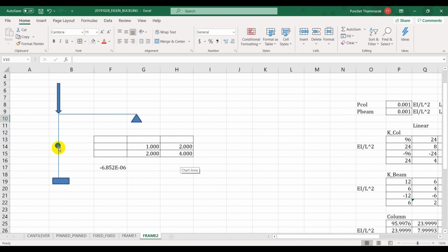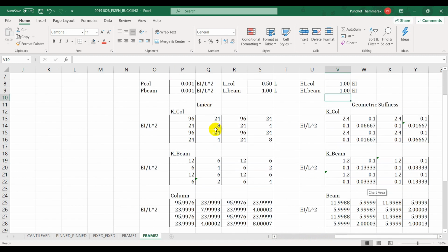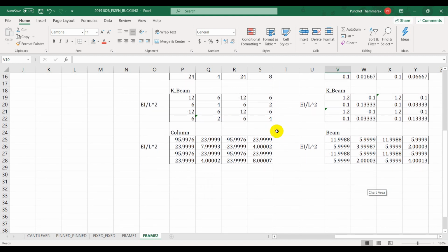If you set it up as 0.4 L for the upper part and 0.6 L, then your stiffness matrix, you're going to make three, right? For the column, you will have two matrices. So you just copy this, and then your EI might be the same, but L could be different, and then you assemble things in. But I am just kind of lazy, so I break it in the middle, and then I just have one stiffness matrix that would work for both members, but you can do it the other way.